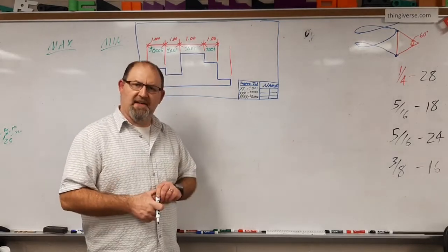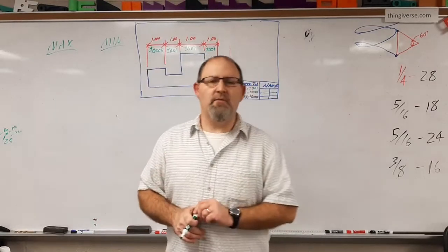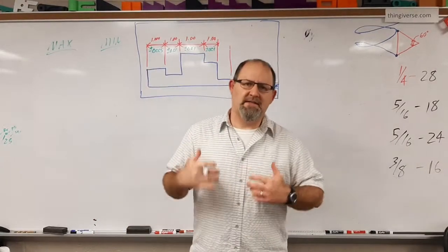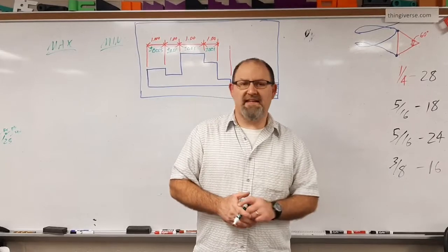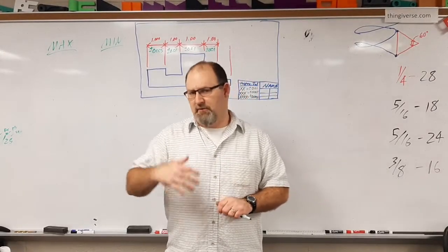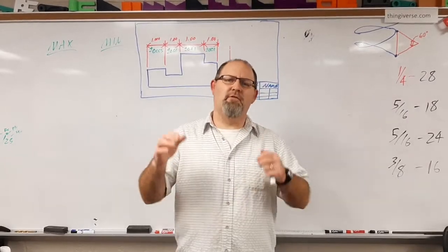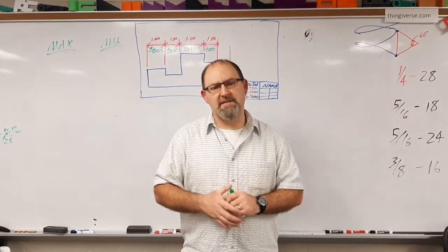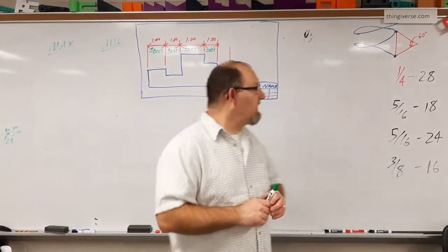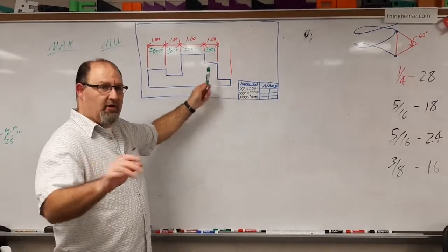All right, so in this video, we're going to be talking about the second style of dimensioning, which is called broken chain dimensions. What it does is combine the chain dimensions that we've looked at, which is another style of dimensioning, and add an overarching control on it, okay? So for the broken chain dimension, I've kept the same part, same tolerance, all that stuff.